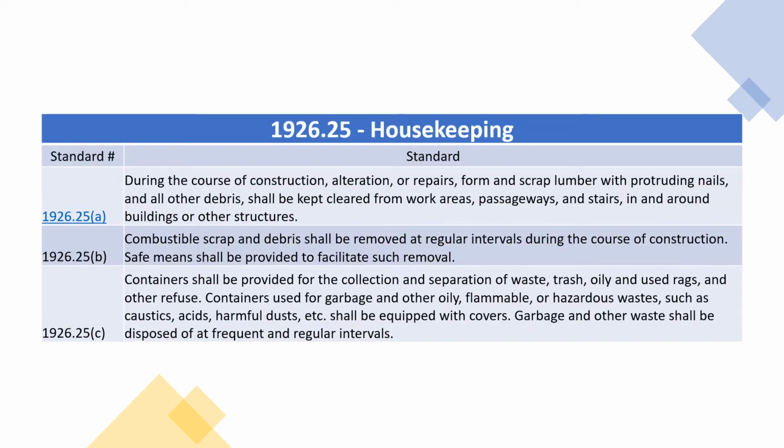1926.25 Housekeeping. (a) During the course of construction, alteration, or repairs, form and scrap lumber with protruding nails, and all other debris, shall be kept cleared from work areas, passageways, and stairs in and around buildings or other structures. (b) Combustible scrap and debris shall be removed at regular intervals during the course of construction. Safe means shall be provided to facilitate such removal.